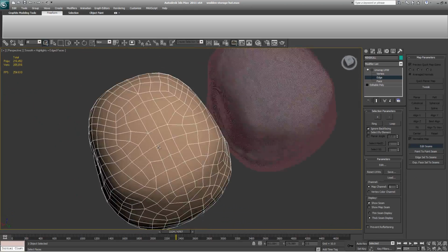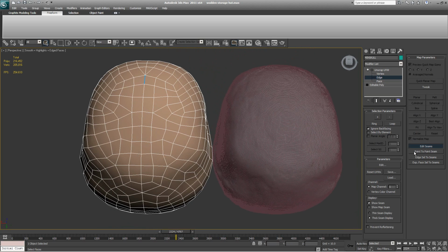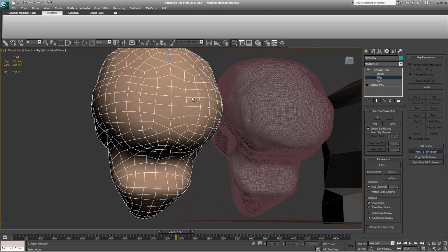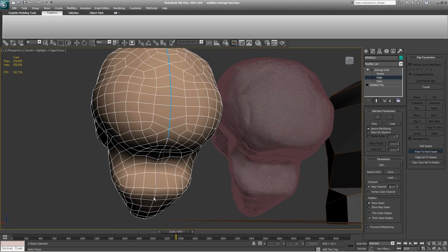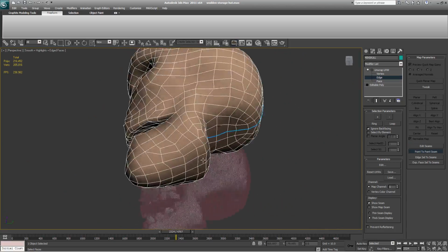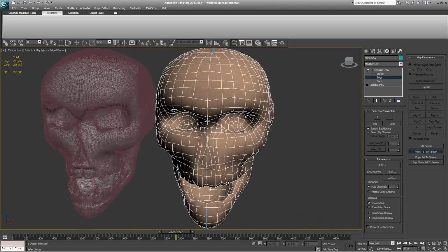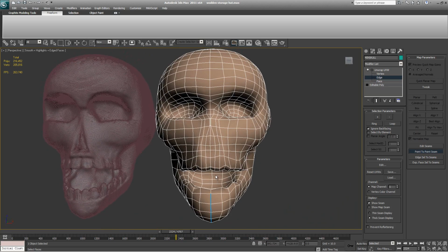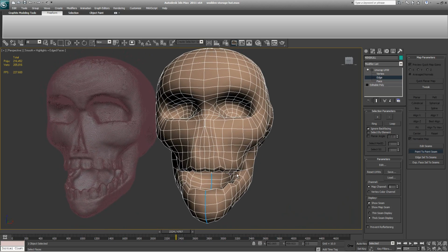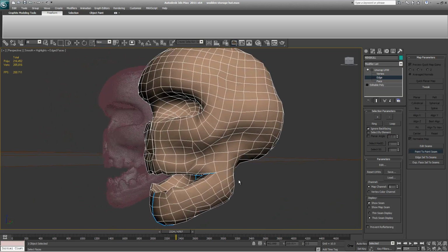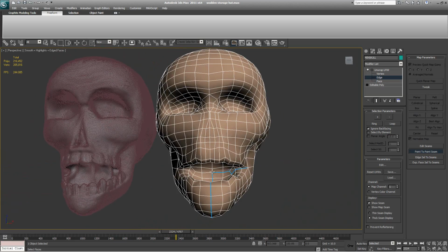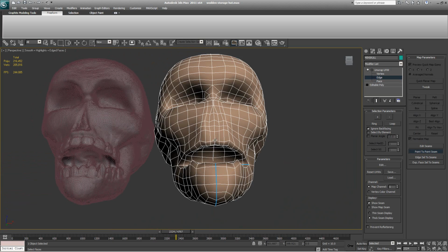The way to do it is to create a T-shape seam, and let's not do edit seams but do point-to-point seams. So click on this point on this vertex and click somewhere here on the bottom, and it will create a seam using the shortest path from the first one. So go down like so. Basically show 3ds Max how to unfold the model. Click over here onto this vertex like so, and then let's return back to here and lay down a seam over here as well.